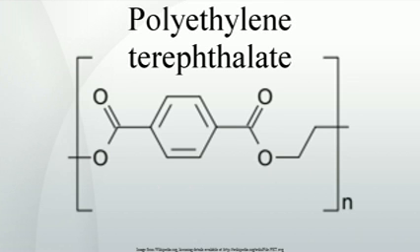Terephthalic acid process. In the terephthalic acid process, esterification of ethylene glycol and terephthalic acid is conducted directly at moderate pressure, 2.7 to 5.5 bar, and high temperature, 220 to 260 DEGC. Water is eliminated in the reaction, and it is also continuously removed by distillation.